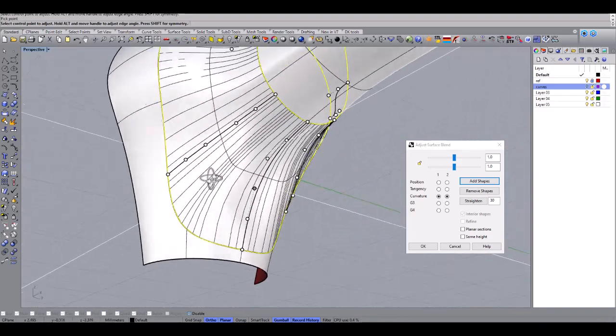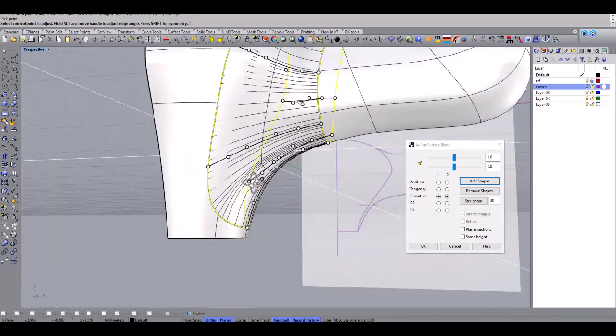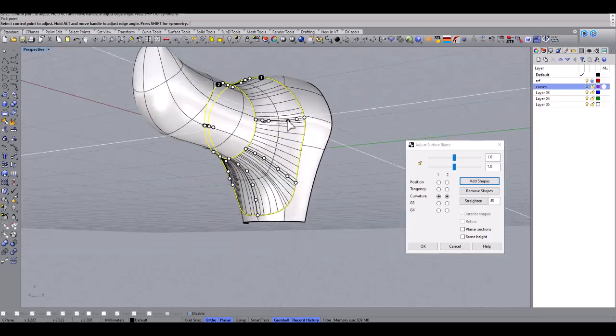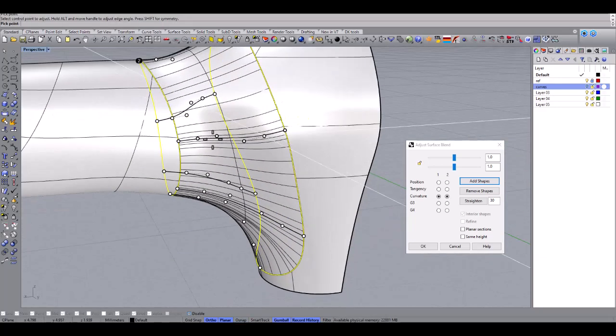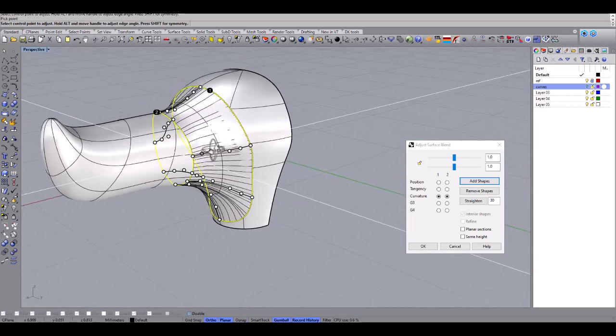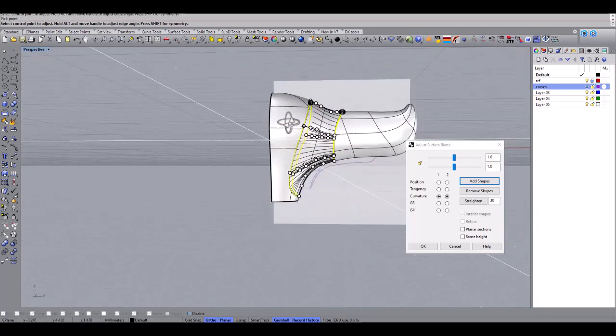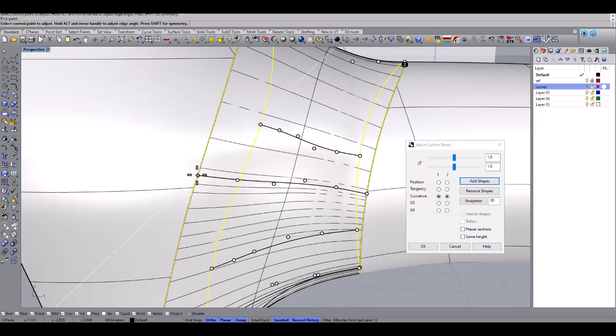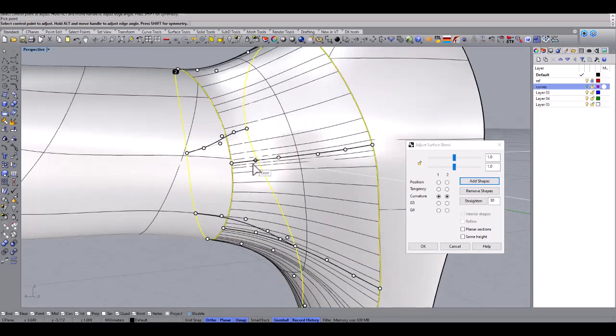So I have a bit more room in this surface here. The same here, I could go and align the handle to the other end. This one too. Hold Alt, click, and Alt again to use the other arm snap.